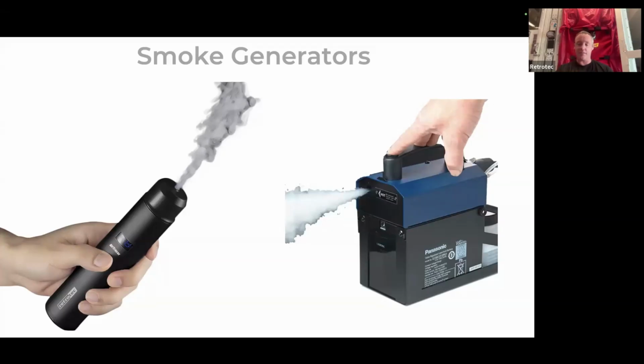If you're pressurizing the house with your blower door, and you have somebody you're working with on the outside of the assembly, then you can see where that fog is escaping from. I've got some examples of how that works too.